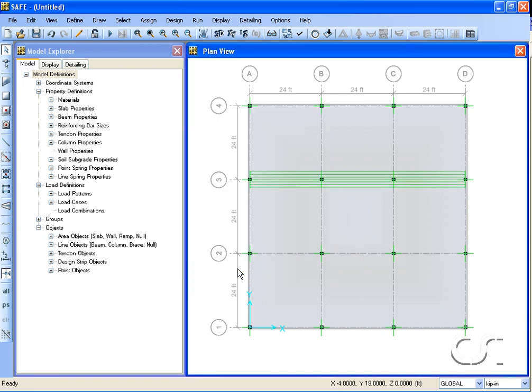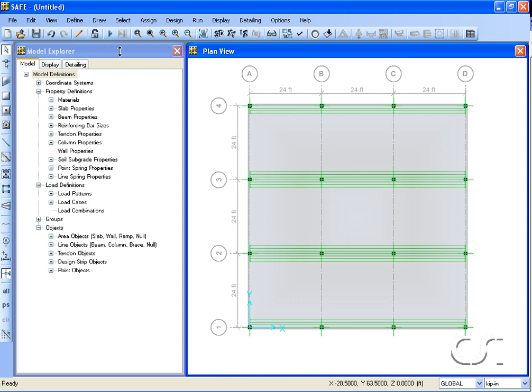We now have a total of 7 tendons over a 60-inch bandwidth. Replicate these banded tendons at other locations. Now we will draw a distributed tendon in the Y direction.